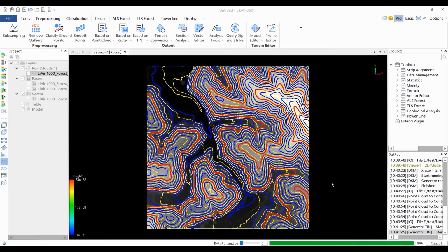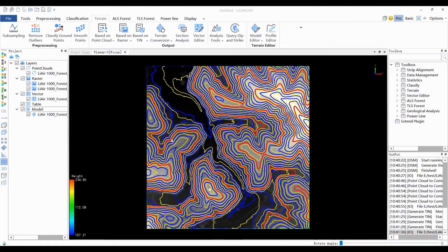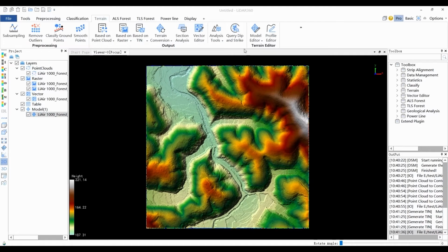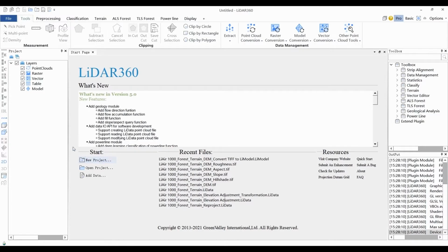The model file stores triangular irregular network models generated by DEM or DSM. The model files can be edited by various operations, such as flatten height, smooth height, repair no data, repair height by variance, repair height and delete height by using the model editor.